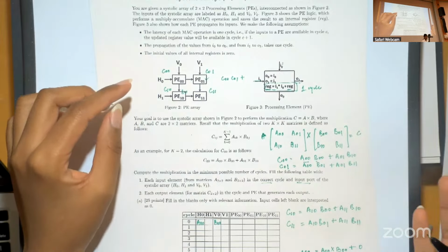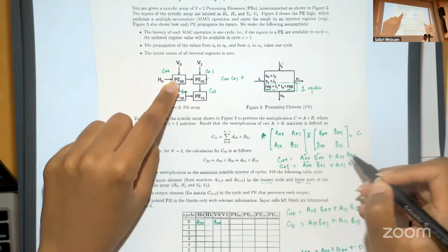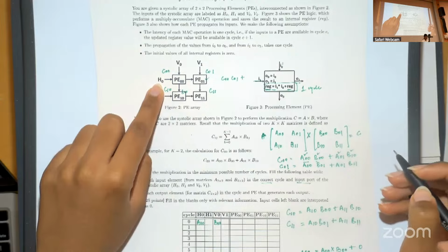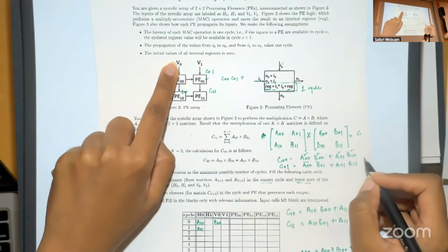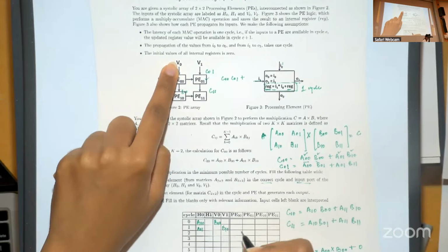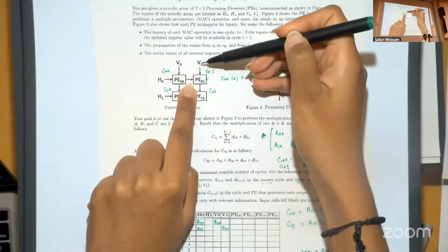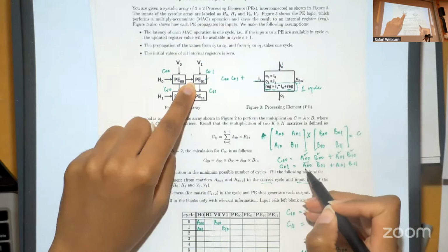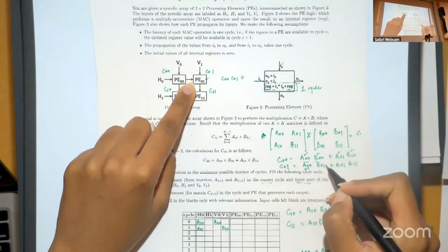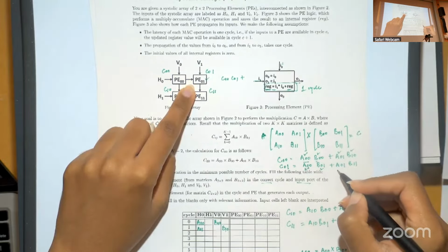Now, what will be the new inputs in this cycle? PE00 calculated this, and now it has to calculate A01 and B10. So as H0, we can pass A01, and as V0, we can pass B10. In this cycle, PE01 has also received an input from PE00, so we will also pass another input from V1. What does PE01 have to compute? It already has this, and it needs B01. And it also needs A01 and B11.